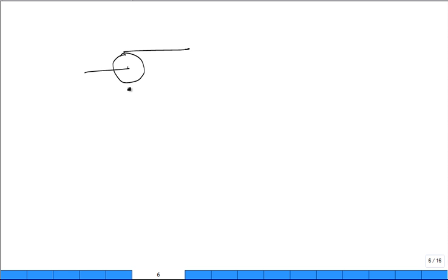They like to have a certain volumetric flow rate, how many GPM or liters per minute or something like that, multiplied by rho and it'll be mass flow rate. And they like to run at a certain RPM, so you feed it a shaft power and that shaft is rotating at a certain RPM. It likes that. It's a sweet spot. It's the best efficiency point.